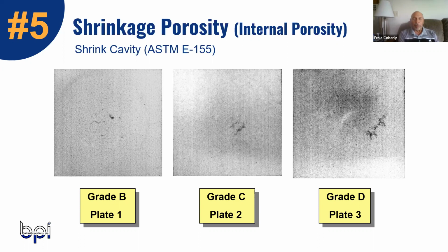Okay. So it's a progression of shrinkage defects, with elongated the least severe, then into the sponge shrinkage, and then into the shrinkage cavity. And these slides here happen to be shrinkage cavity. So you've actually failed to get metal into that portion of the part, and it's isolated a cavity. Again, if you look at that grade D slide, you see that dark area all around the cavity. That's back to more of what they would call sponge shrinkage.